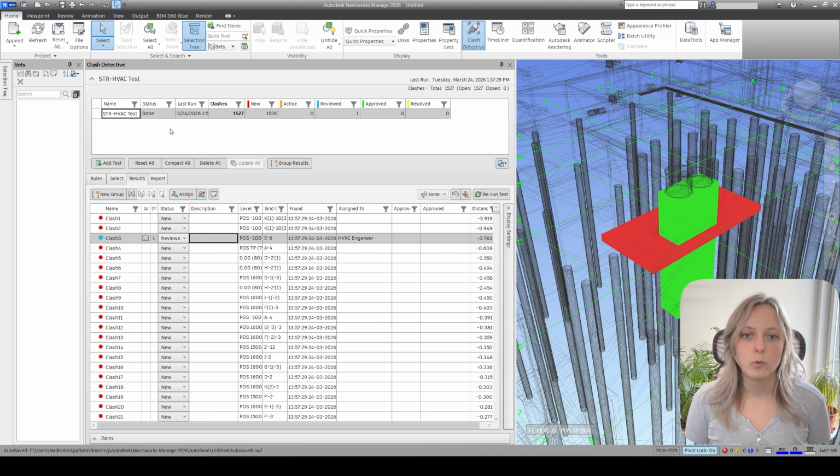But generally, whenever I'm coordinating the projects, first, before even entering Navisworks, I would pay attention to those visible clashes, because once you do the first checkup of the model, you kind of browse through it, you will see some of the biggest clashes. Of course, you will miss a lot of these smaller clashes, but there are some clashes in the project that are always visible.